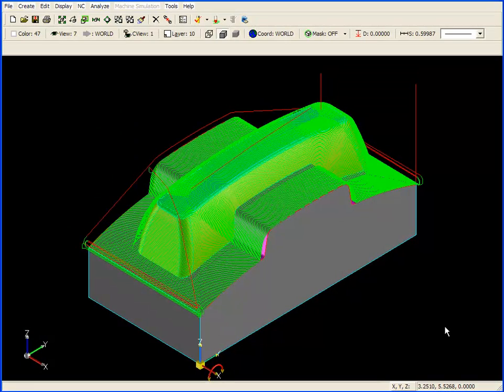Here's the previous 3D offset tool path modified with the tangential ramping move changed to direct and the retract strategy changed to shortest route. As you can see, we don't have the same up and down retract moves that we had before. All retract moves are taking the shortest route to get to the next position.